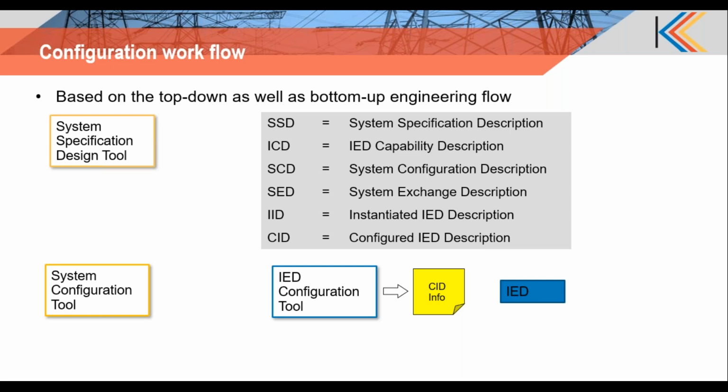But now the problem is, the one setting that goes in is the IP address. Additionally, there will be a lot of settings specific to the IED functionality that have to go into the device during the configuration, because that has a dependency on the project and the site. So that's primarily the instantiation of the IED. You need to load individual settings into each IED. That is typically taken care of by your IED configuration tool.